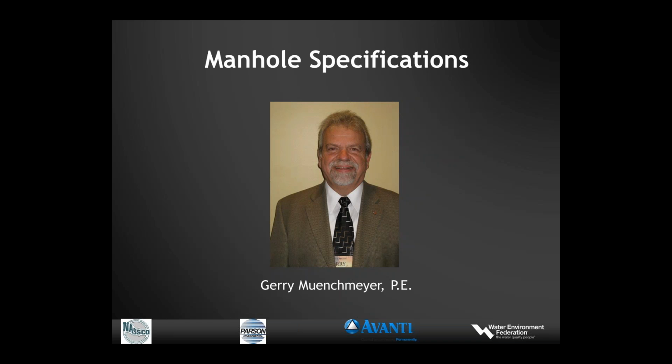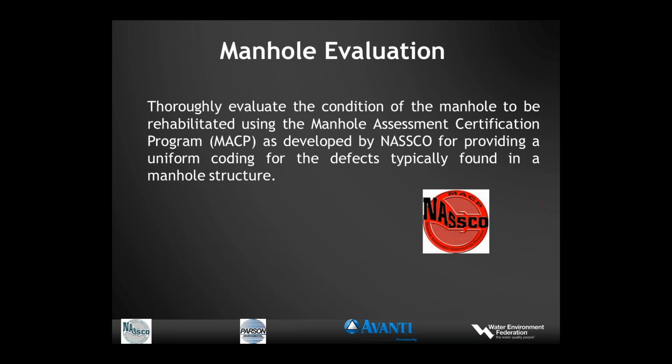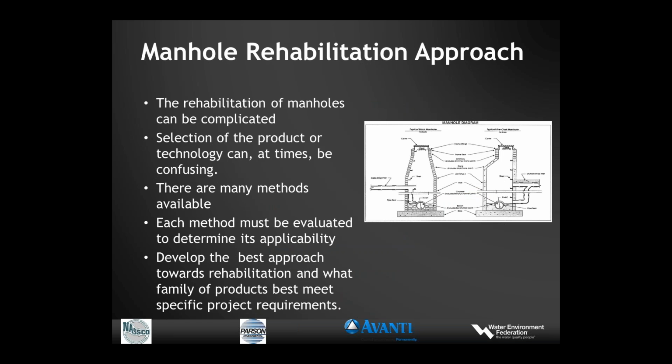What I'd like to do with the manhole side of this presentation is not get redundant to what Lynn just went through. He went through all the details. The specifications are set up similar in terms of inspection, quality controls, and whatnot. But I'd like to start off with what's important with the manholes. One, manhole rehabilitation doesn't involve one technology. It involves multiple technologies. As a general rule, you have 7 different components, anything from the casting to the cone, to the bench, to the invert, to a variety of different components of the manhole. Each one of these has different rehabilitation approaches, and in many cases, a project may include one or more of these technologies.